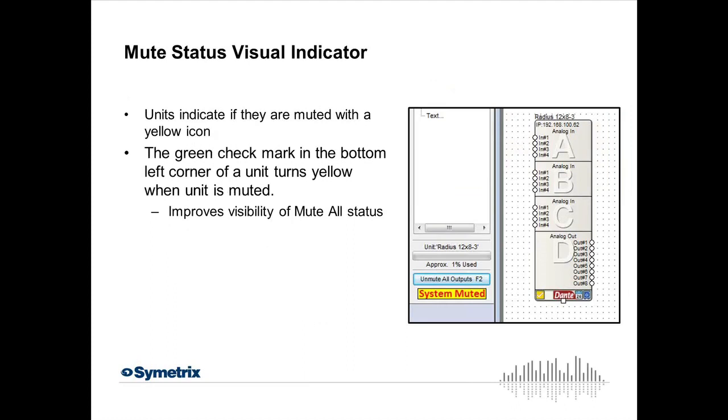Along those lines, the system has an emergency mute, which is F2, and that also gets engaged when you push the file to the hardware. Of course, all outputs get muted, so you don't hear weird anomalies as boxes get updated. However, what we see fairly regularly is that before clicking OK and the system ramping up after pushing the file, someone maybe clicks and drills into a DSP without clicking that OK, and the system gets stuck in a muted state.